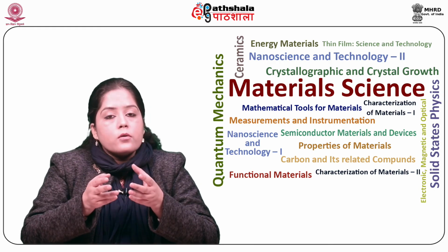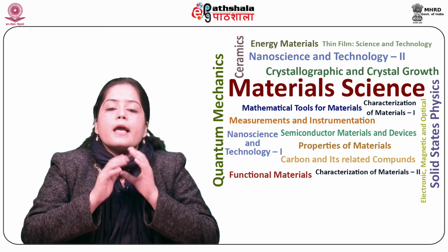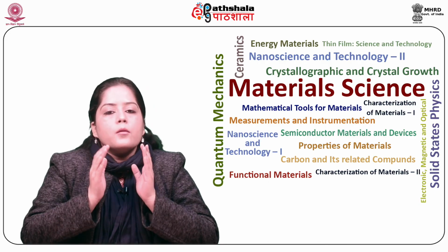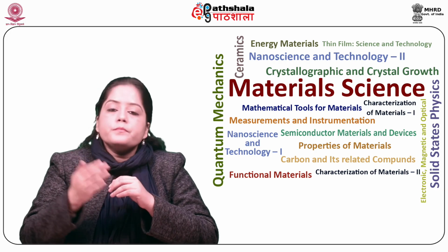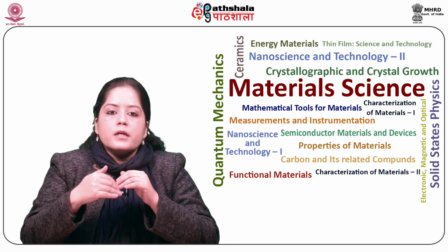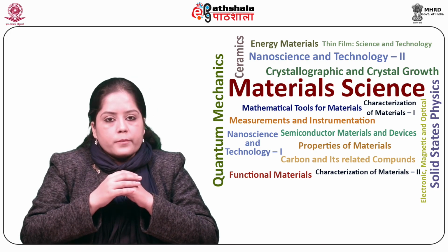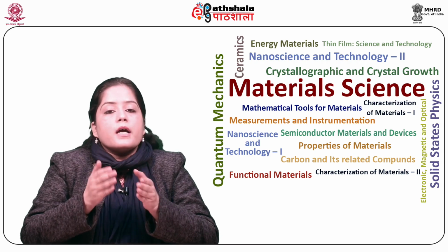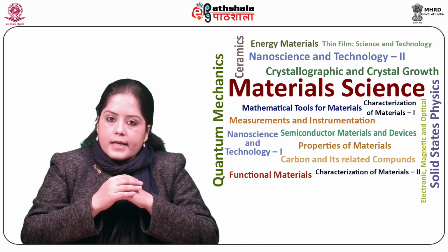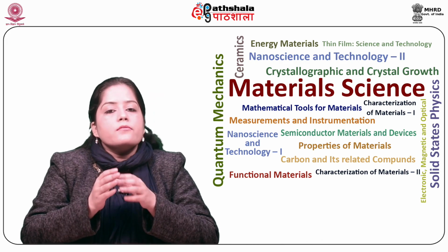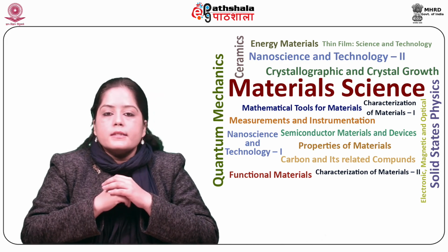And the excitons, what are these? Excitons are bound hole-electron pairs. So below the band gap, due to binding energy, we have hydrogen-like quasi-particle, hydrogen-like energy states. So we have the effective Bohr diameter,